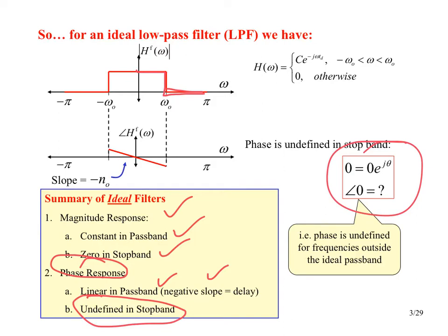And to be honest, even though these things don't exist, as we'll see in just a minute, when we're thinking at the high level of how to do some signal processing task, we often work it out just thinking it through, thinking, okay, imagine I have an ideal low-pass filter. How would this work? If you can't get things to work theoretically, imagining that you have access to an ideal filter, you'll never get it to work in the real world. So you often think things through in terms of an ideal low-pass filter, and then you go back and say, all right, what do I really need to make this happen that I can actually build?